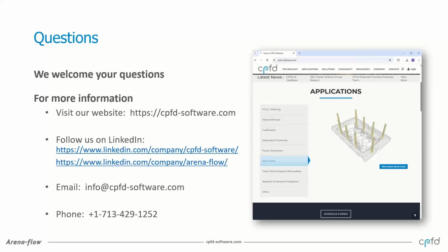Yes, you can, and that is a very neat feature. You can actually cycle through sand levels, which can help to determine if there is a core quality related improvement from having maybe run a little lower than expected. This kind of sweet spot, sand level, height, will give you the optimal core quality. So yes, you can definitely cycle through sand levels or sand heights using the previous and then just restart a new blow.